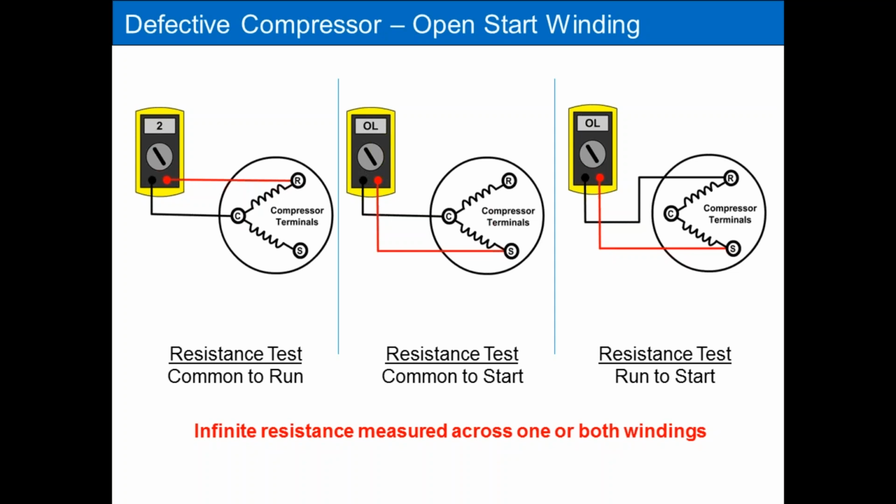But if you don't see that little M on your meter, you're in a dark location, and remember sometimes you're working upside down and backwards on a floor and not in the best lit area, you may overlook the little M, meaning you're reading in the million ohm range. Don't let that fool you. It's fooled me, so I can only imagine it's fooled some other people as well.